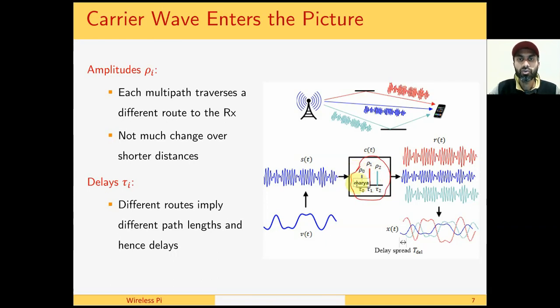Recall that convolution of a signal with a unit impulse is the signal itself. Since our same transmitted signal is arriving at the receiver, we say that it is convolved with a unit impulse. And it is convolved with a unit impulse with a different delay because this path is arriving after a little delay. The same goes for the third path, which has the largest delayed impulse. And after the down conversion at the receiver, we can see that these paths are interfering with each other in different manner, details of which we will see now.